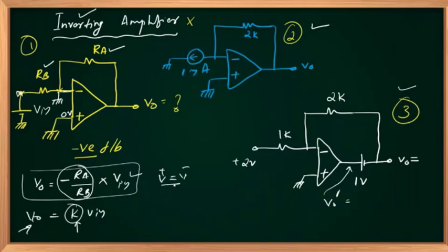You can analyze the circuit many ways. Let us say current IA is flowing into that node, and there is no current into the op-amp. So IA is nothing but, in this polarity, by Ohm's law, V out, this end potential, minus the potential at the other end of RA, that is 0.